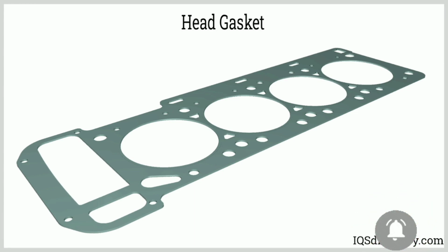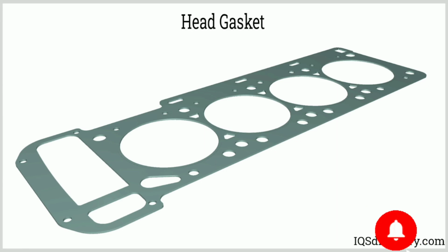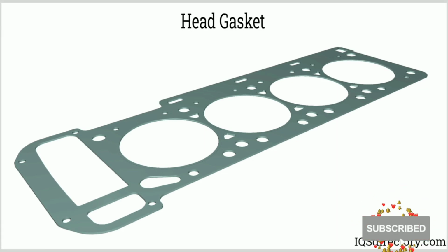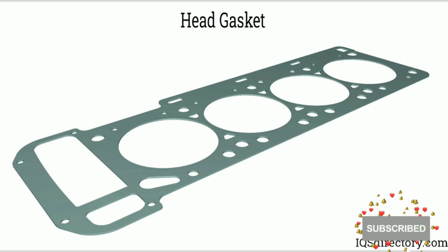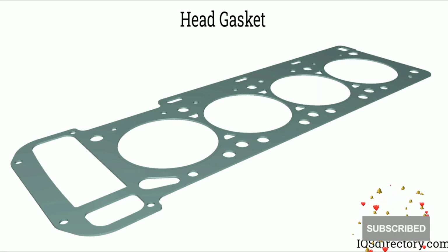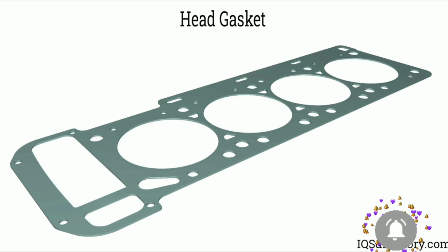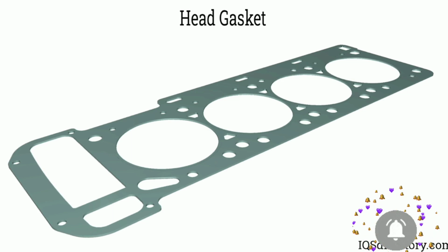This is a cylinder head gasket. It is located between the cylinder head and the cylinder block. Its purpose is to seal the combustion chamber gas tight and to prevent coolant or engine oil from escaping into the combustion chamber. A failure or malfunction of the cylinder head gasket leads to engine overheating and other engine faults or other possible problems such as excessive blue smoke. When there is a problem with the cylinder head gasket, your engine will release excessive blue smoke.